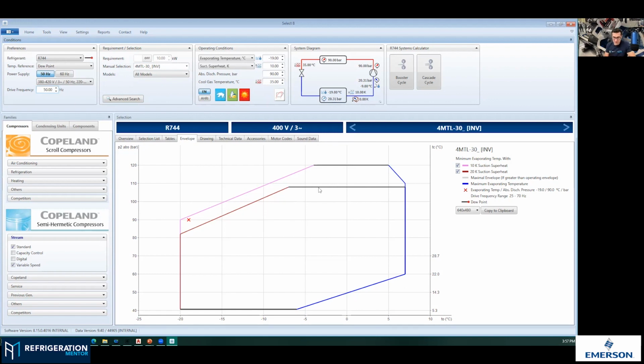And I think I was told this before, but so everybody knows and understands: just putting the drive on, connecting a drive to a compressor, you will reduce the operation envelope. Is that correct? Yeah, that's correct. You run at a little bit lower efficiency and it heats up the motor more, and you cannot get, let's say, compressor input power on the same level as a solo compressor without the drive. And it's different from compressor to compressor how much this reduction is.